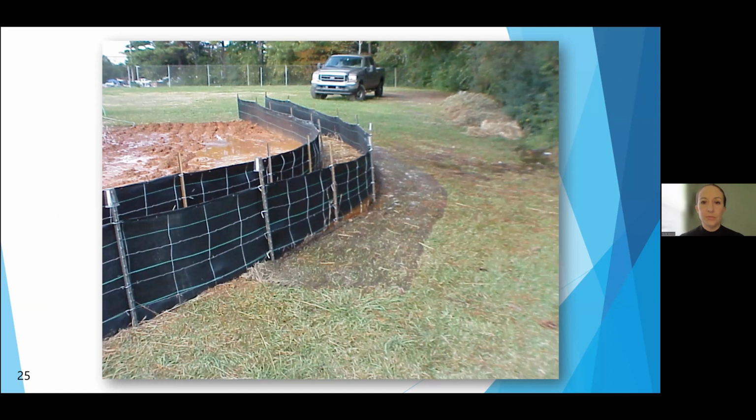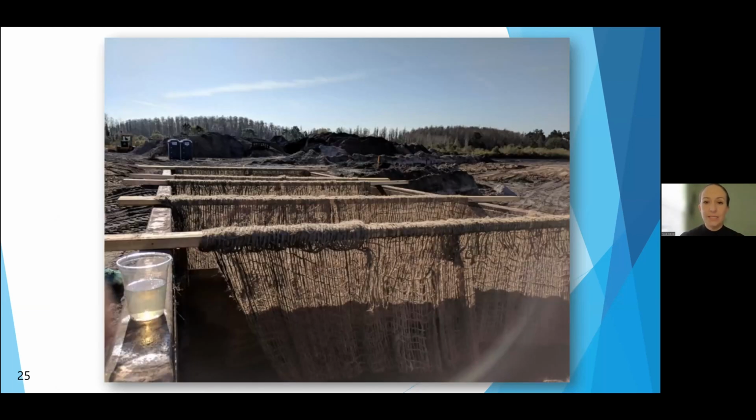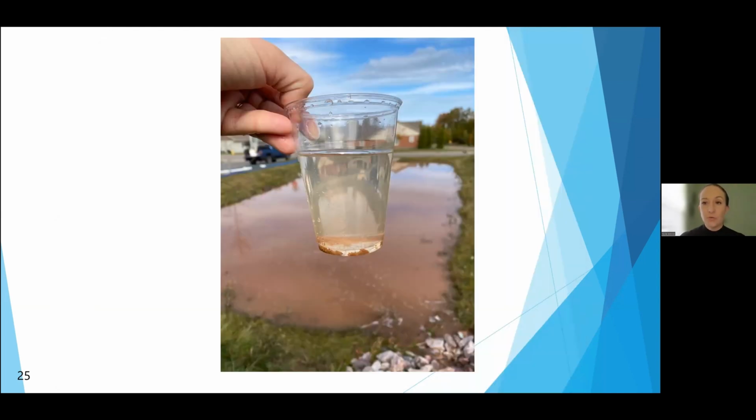For particle collection, you can also use straw bales, silt fence, again that jute matting. There's just a lot of different ways that you can collect the particles. Here we had used a tank as a temporary sediment basin, and strung jute particle curtains in it to help collect that flock. You can, of course, just use a basin and let those particles settle, if you have an area where you can slow the flow and drop those particles out.